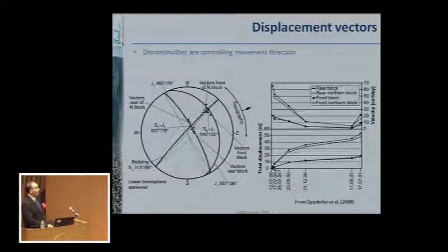And then what was interesting, it is that if you look at the failure, this is a representation of the direction of the different fracture that you find in the rock mass. There is one which is vertical. This one is going down there. This is like a circle. It's like an intersection of a plane with a sphere. And this is going down, and this is a vertical one. And this is the movement, the vector of the movement in 3D, projected on this plane.